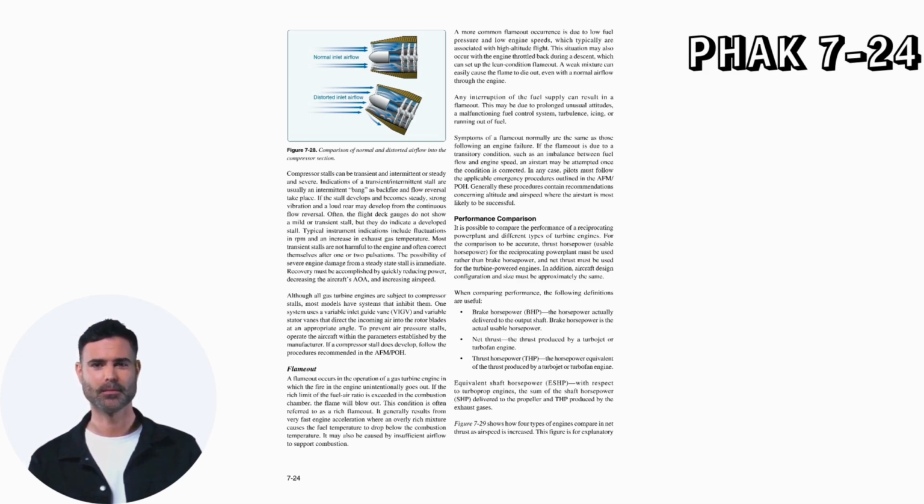Performance comparison. It is possible to compare the performance of a reciprocating power plant and different types of turbine engines. For the comparison to be accurate, thrust horsepower, usable horsepower, for the reciprocating power plant must be used rather than brake horsepower, and net thrust must be used for the turbine-powered engines. In addition, aircraft design configuration and size must be approximately the same. When comparing performance, the following definitions are useful.